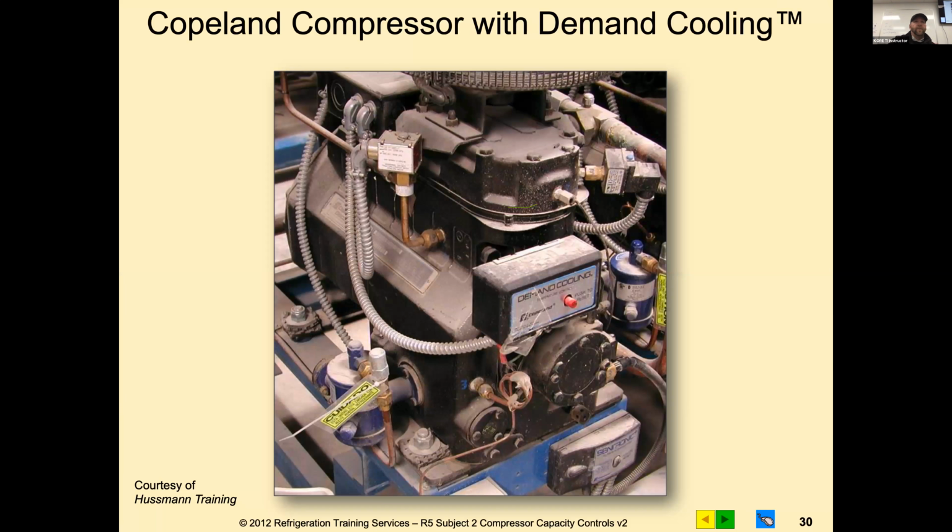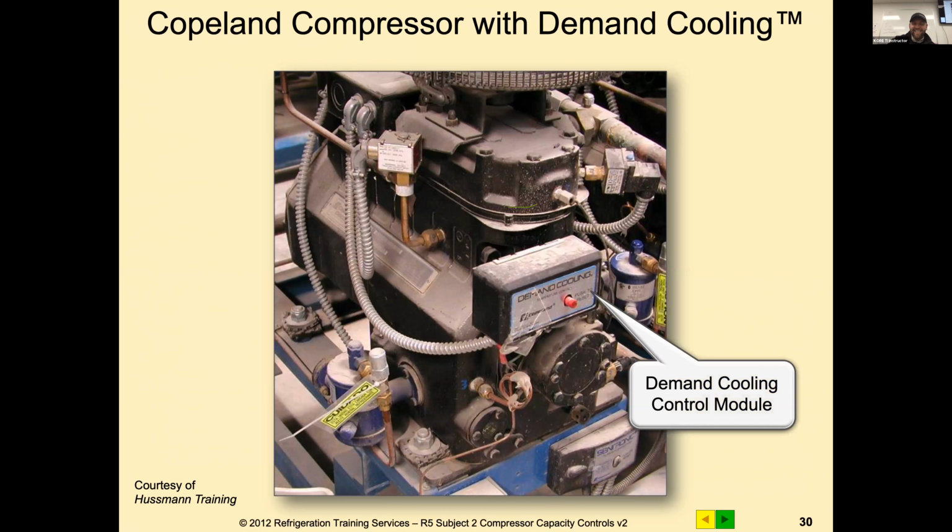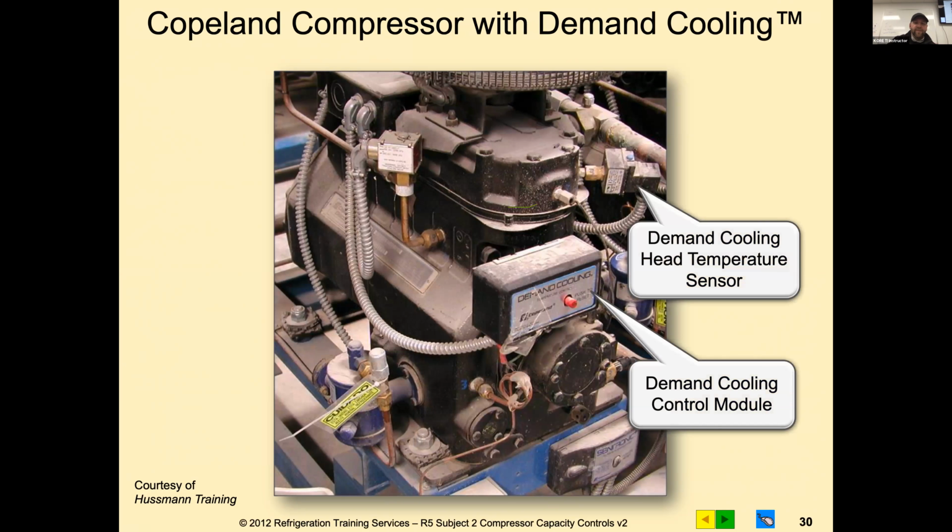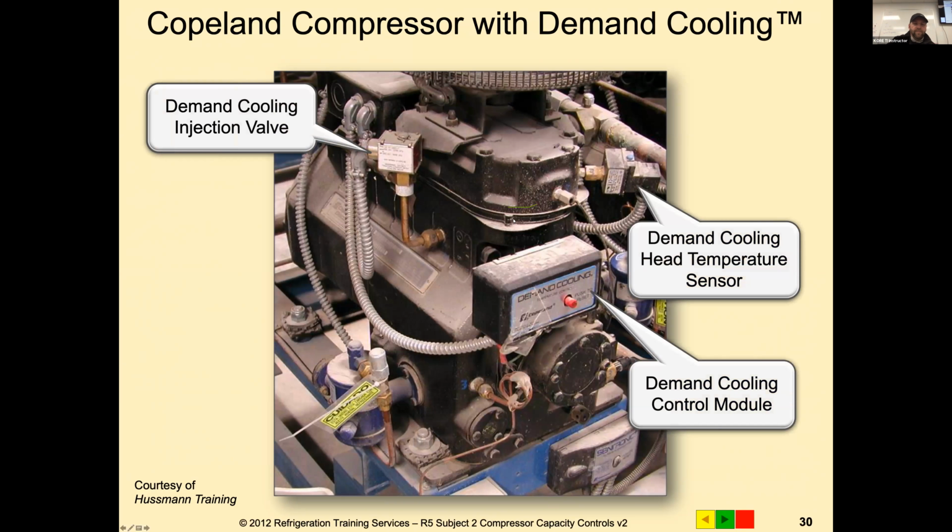I'm sure everybody has, has anybody not seen this? Old style. Don't be afraid. So that is not a demand cooling valve. That is a fan control. The temperature sensor, that's actually a head pressure control with a manual reset. The temperature sensor, if you guys can see my cursor, is right here, right there at the top of the head. So there's your injection valve. It goes in and flashes the chamber right before compression.